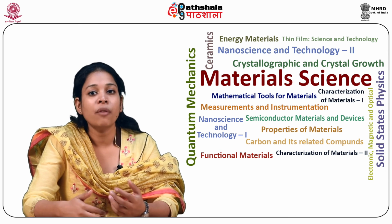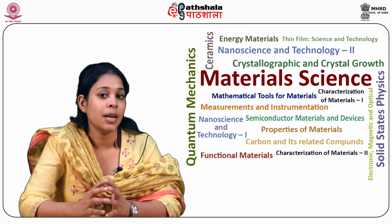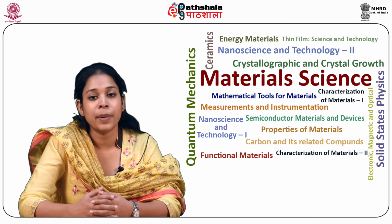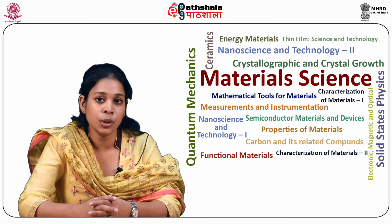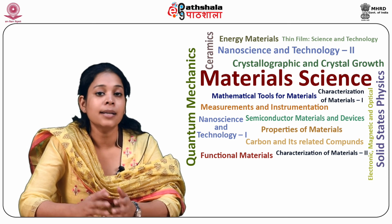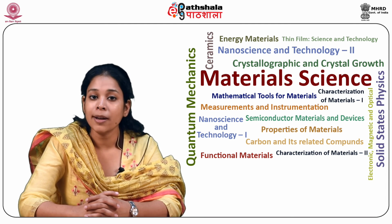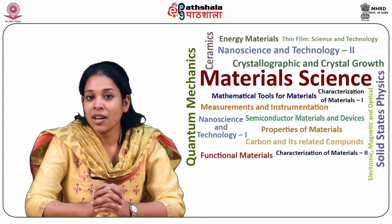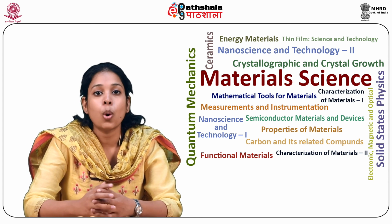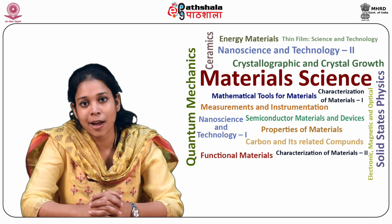So in this module, two of the important structural ceramics, that is alumina and zirconia, are described. So the first is alumina. In alumina, we understood that the alpha alumina has a rhombohedral structure with the space group, which is already detailed in this module. The lattice parameter at room temperature when referred to hexagonal axes are A is 0.4759 nanometers and C is 1.299 nanometers with a coordination number as 6. The structure is best described as an AB-AB hexagonal close packing stacking of the O2 minus ions with Al3 plus ions located at 2/3 of the octahedral interstitial sites.